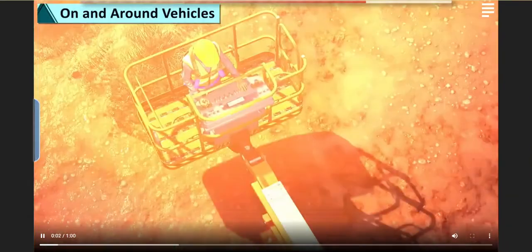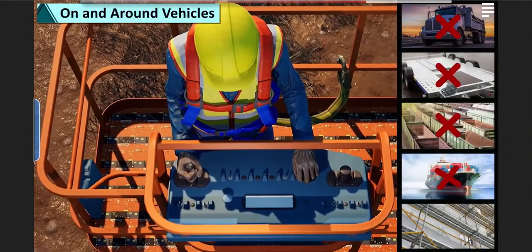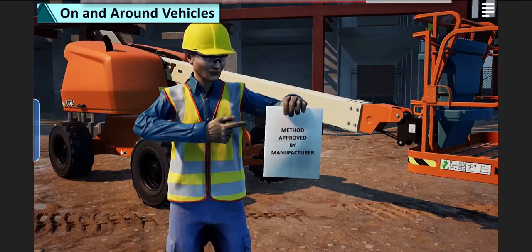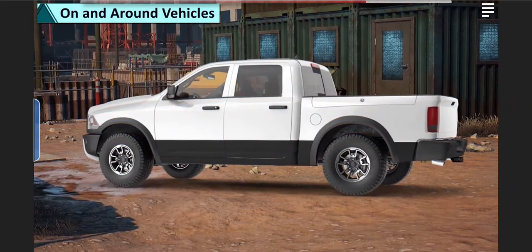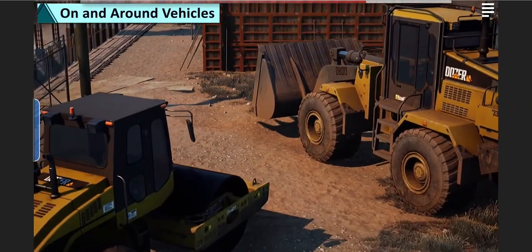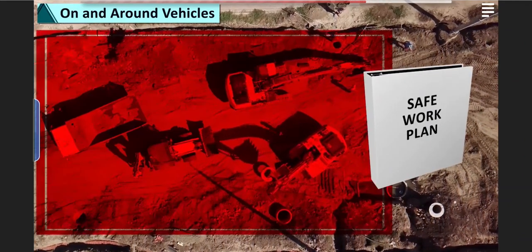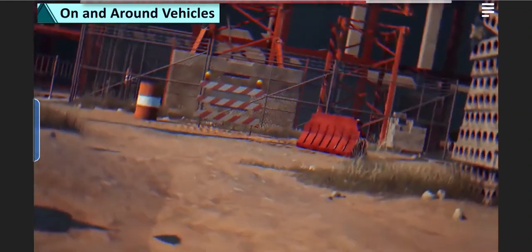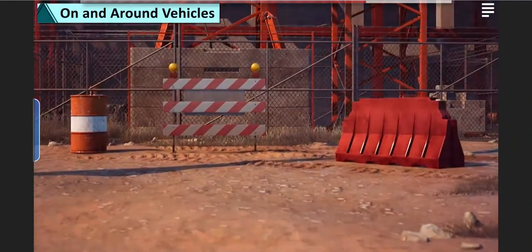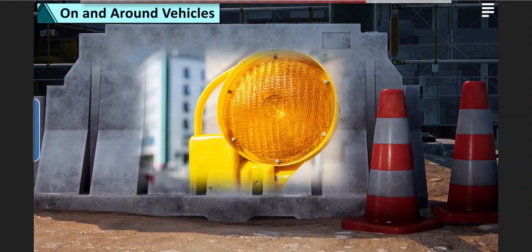Except for loading and unloading, never drive or operate a MEWP from a position on a vehicle, trailer, rail car, boat, scaffold, or similar equipment unless the application and method are approved in writing by the manufacturer. If vehicles or other moving equipment are present on the worksite while MEWP operations are underway, special precautions must be taken. The Safe Work Plan should identify all hazards related to the traffic or equipment and how to protect against them. Use and observe any warnings and safety devices required by the employer or local ordinance, including barricades, ropes, cones, flags and flaggers, lights, and safety signs.